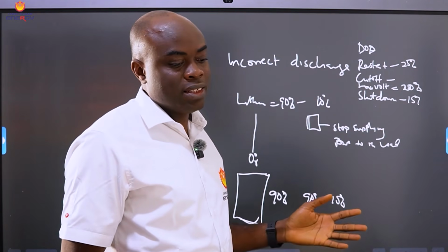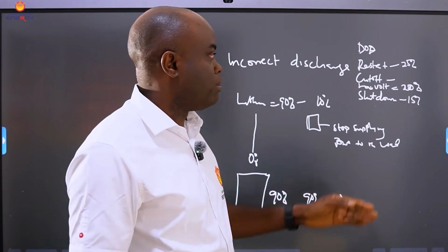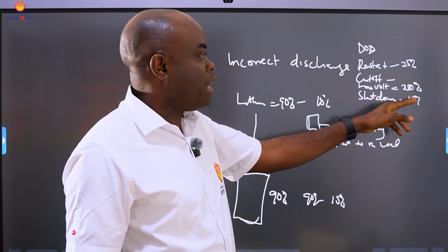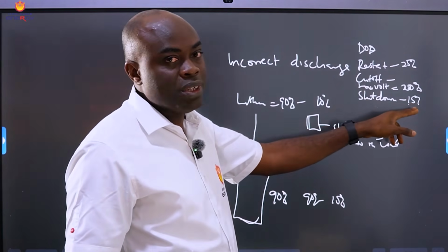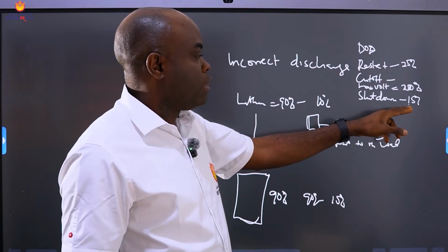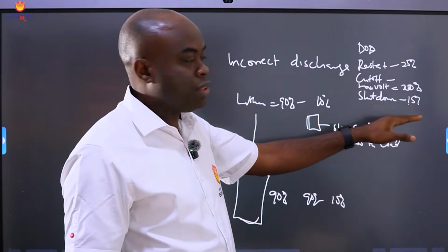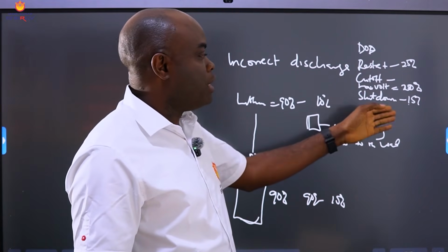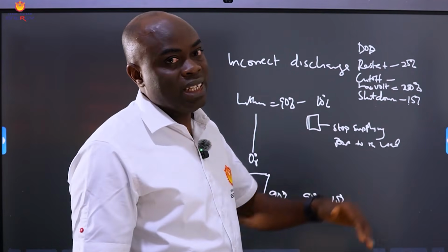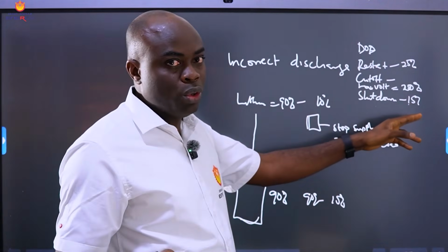Of course, if for example you are using just grid, you don't have a solar system, and your grid is not stable in the location you are in, when your battery is discharged to 15% and the load is cut off, once it detects grid, it begins to charge the battery. Of course, it's meant to bypass to power your load. So if it bypasses and is powering your load and is charging your battery, it doesn't take from the battery when the grid goes off.